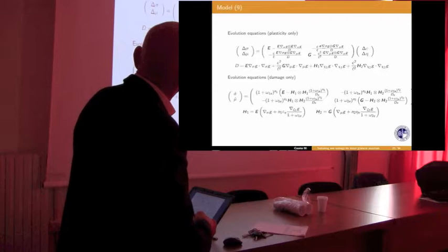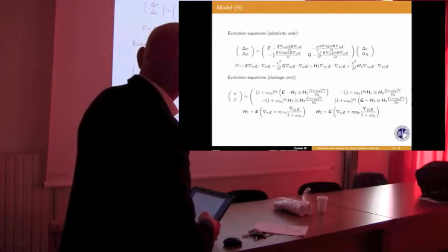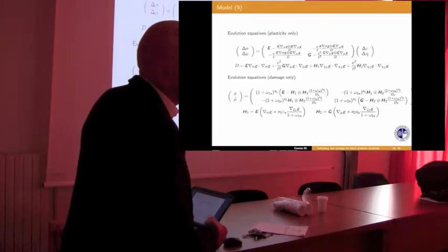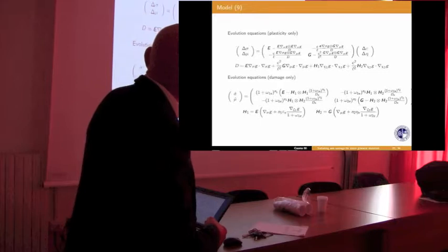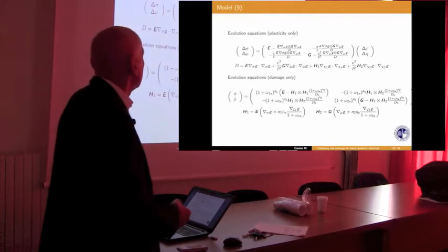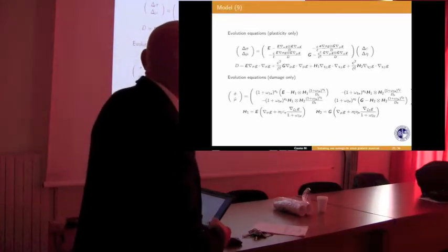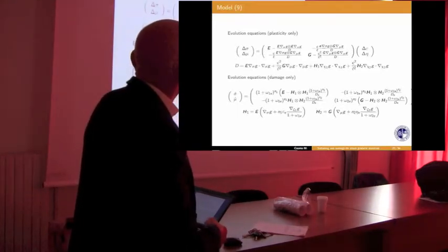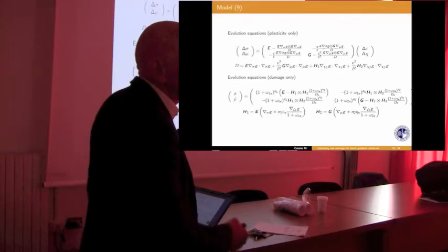So when you have nonlinear evolution, these coupling terms appear. The coefficient D at the denominator has inside this term, which is a scalar. This is an effective hardening modulus. It is interesting because it contains the hardening modulus for the local and for the non-local stresses, and according to the sign of the two, the sum can be positive or negative.